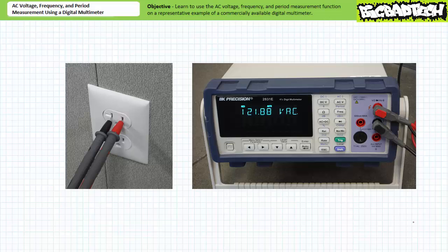Note the DMM is displaying the RMS or effective voltage of this AC voltage waveform and not the peak or peak-to-peak value. I say again, all DMMs, all the time, always measure RMS or effective voltage unless explicitly forced into performing some other function. Note our socket has 3 holes, and as currently illustrated, this DMM is measuring an effective differential of 120 volts across the top 2.